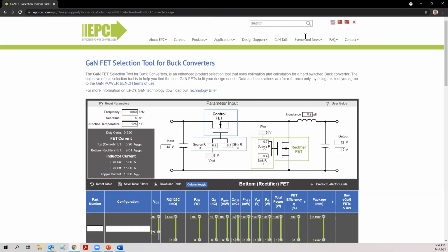So circling back to that early question about the current, what was the formula for current calculation? It was the plane current, the current for the plane. I don't remember by heart. Usually, what I do, I use the physics formula, which is telling me that the resistance is the resistivity multiplied by the length and divided by the area, and the area is the section of the plane. So if you have a 2 ounce plane, the section will be double compared to a 1 ounce plane. That means your resistance will be lower.